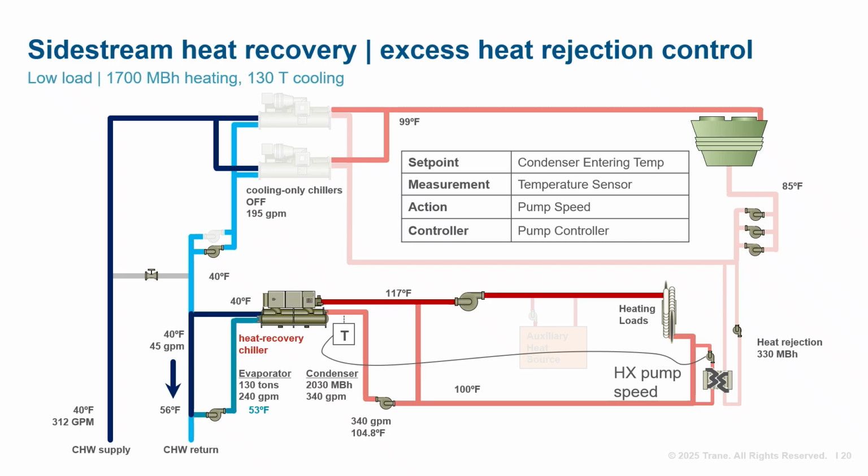Through the addition of system-level control, both the heating and cooling demands can be met. A chiller bypass around the cooling-only chillers could be added, increasing cost and transition complexity. Today's chillers often permit cold water flow through the evaporator while disabled.